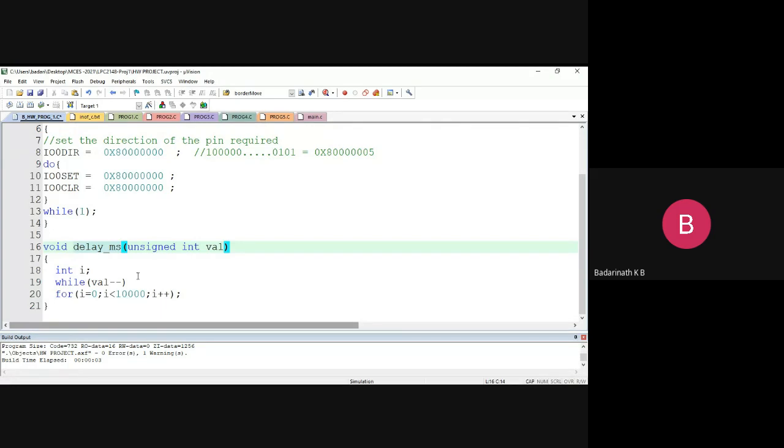Basic ticks. Now, how do they produce the basic ticks? Because the operating system is nothing but what? A software running on a microcontroller. Yes or no? So the basic ticks will be produced by a program like this, and they would have tested for a particular hardware, for a particular microcontroller, how to produce a particular millisecond. It's a trial and error. So we did a trial and error on our board. For this value, approximately we were getting 1 millisecond.